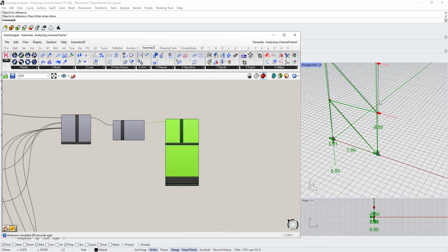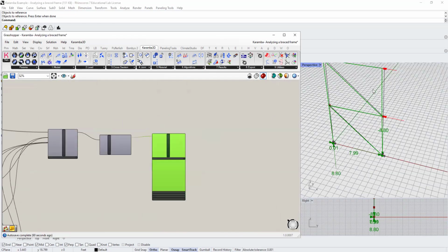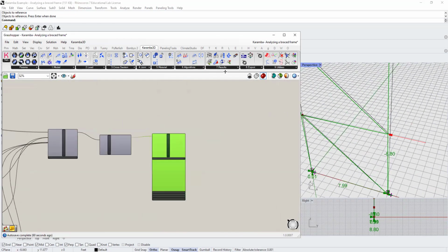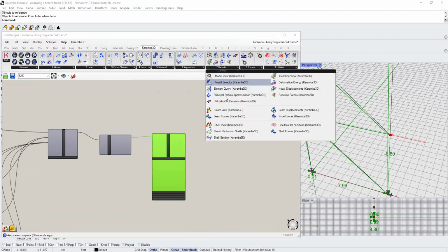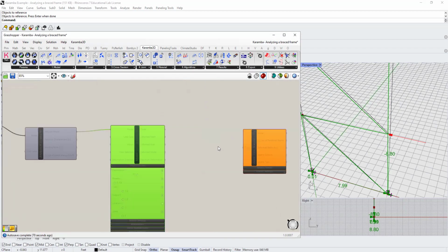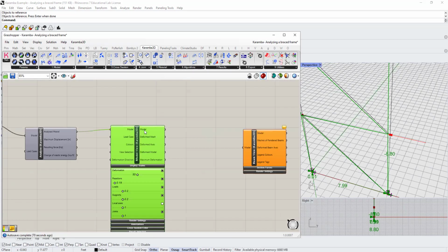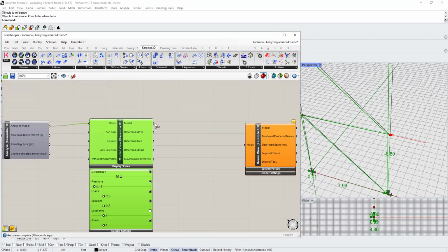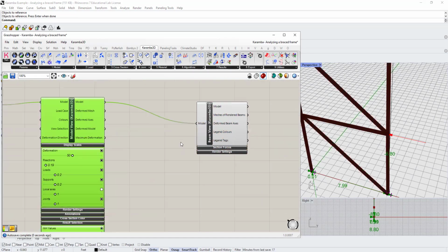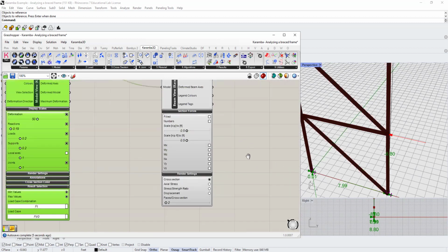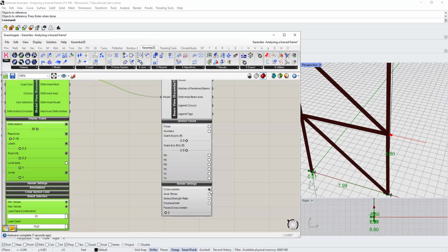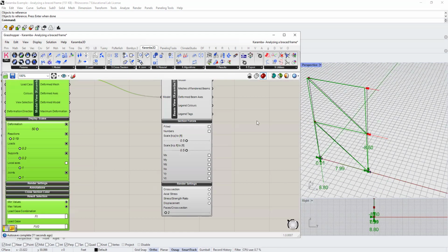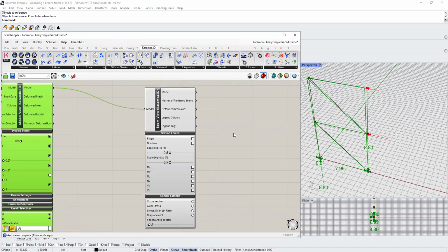Now, in the next step, we want to actually see the loads in each element. So we go to the results, drag and drop the beam view. I connect this model where I picked FT here and connect it to the beam view. And then here, I open up these two drop-down lists. Here you see this cross-section. I'm going to check it off. I don't want to see the cross-sections because I didn't define any cross-section, and Karamba is going to just visualize the default.